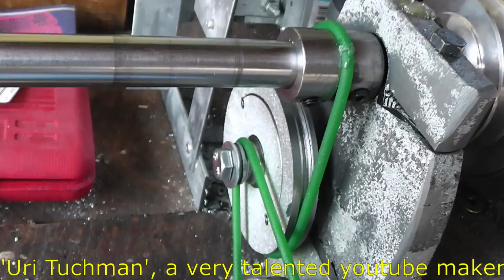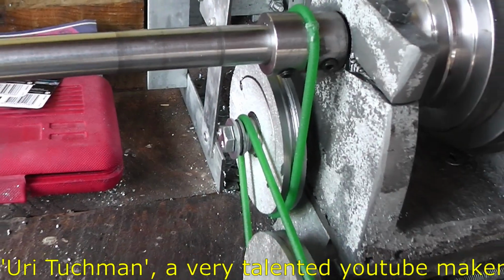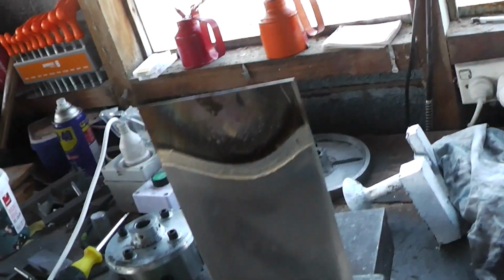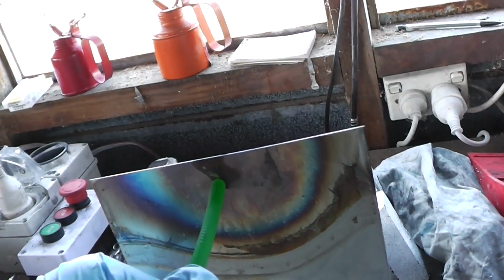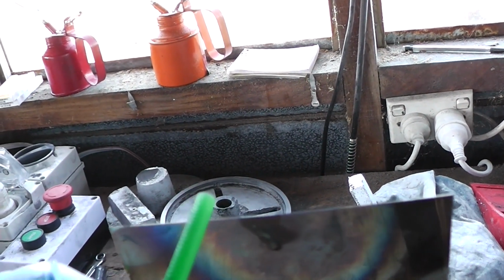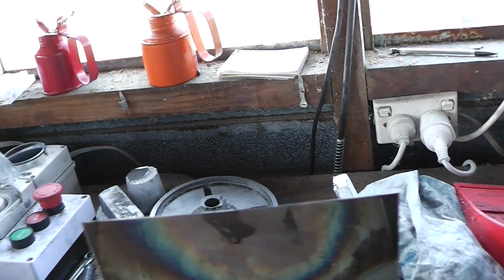As for this green round belt, I got the idea from Yuri Tushman. Sorry, I don't know how to pronounce it. I took inspiration from him on how to join them. I used my blowtorch setup to heat up the metal there, hence the discoloration. And once the metal was good and hot, I grabbed both ends of this, pressed them against the metal to melt it slightly, and then raised them together to join the two ends. Imagine there's another bit of green belt connecting to there.